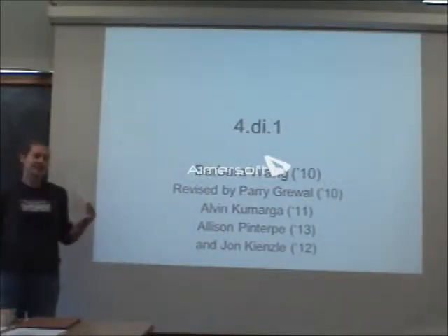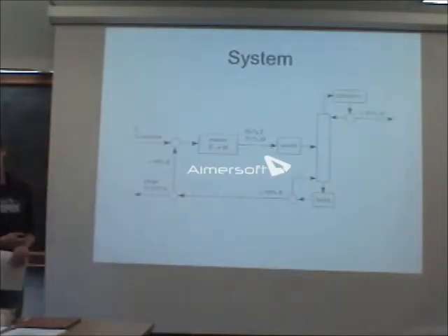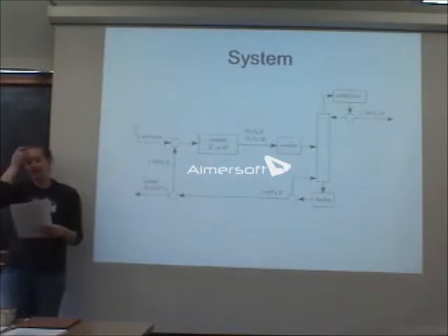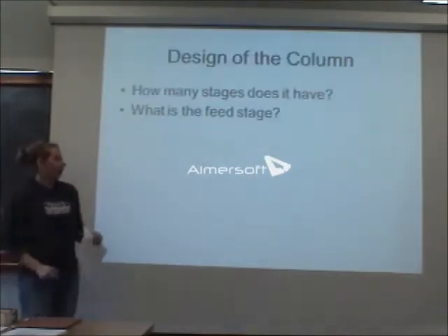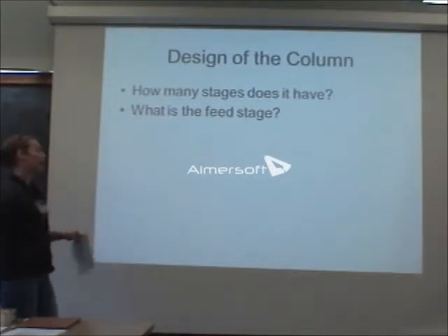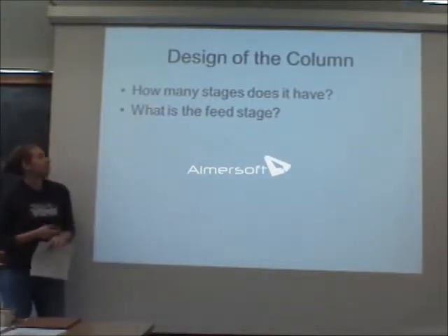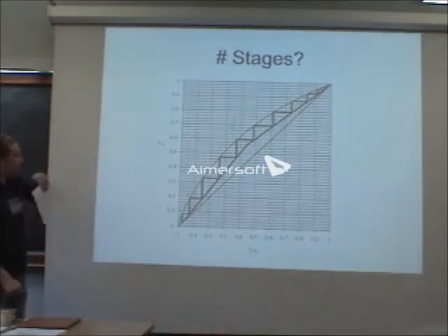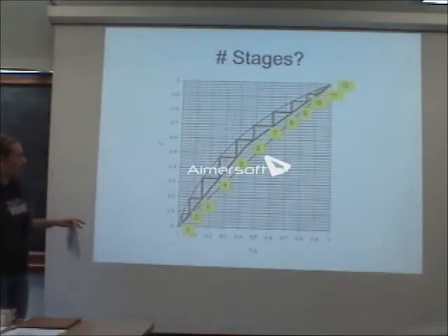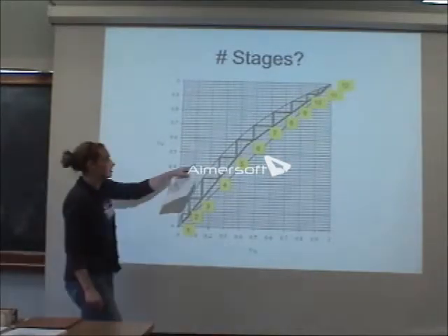4.di.1. Distillation columns. Alright, so we have this system here and we were asked to do a lot of things, so bear with me, we're going to try and go through this and get everything done. First thing we have to do: how many stages does our distillation column have and what is the feed stage? Let's go ahead and count off stages. So I got 12 stages with feed stage of 6.